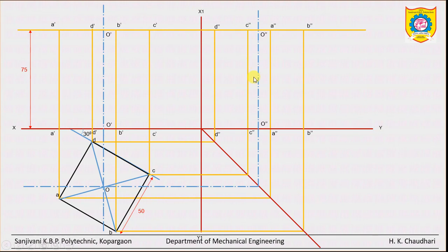Clear? Now we have to draw the intersecting prism. So draw here by taking 37.5, half the distance, because the axes of both prisms bisect each other. So we have taken half of this 75. Draw here, we get the center point and such a square, the left face. This is the left and right face, the overlapping face.